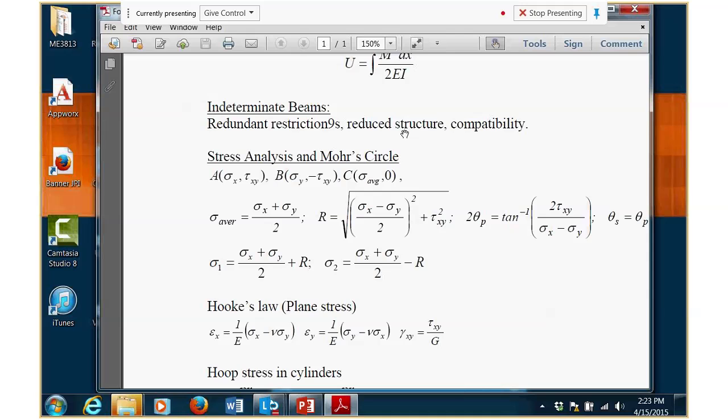All right. Okay, then it's chapter 7. Here it involves both the scale and the equations or formulas. The goal for us is, whenever I give you a stress at one point, oftentimes a plane stress, we'll need to know in which direction you have the principal stresses, the first principal and second principal, and which direction you have the maximum shear stress. So you need to be able to calculate all these values: what's sigma 1, what's sigma 2, what's the maximum shear, and at which angle, which direction, it takes the maximum.